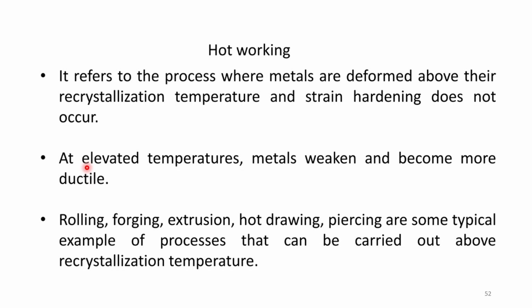And at elevated temperatures, metals weaken and become more ductile. Because of the higher ductility, the deformation of materials becomes easier at temperatures above the recrystallization temperature, so less force is required compared to cold working, and the rolls that are used will also deform less.